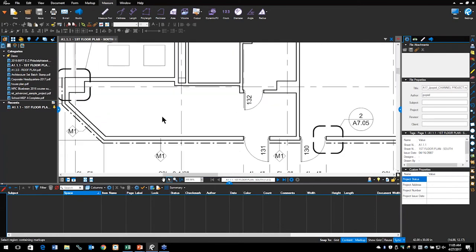So I have a file open here, and you'll notice in this particular room there are a couple of openings, and so we have to close those off. It kind of almost works like hatching in other programs. So up here on the top of the screen, in the command bar, so again, just for logistics, the top of the screen here is the command bar, and as you click on different tabs at the top, you'll see that the icons on the right change, the icons on the left don't.